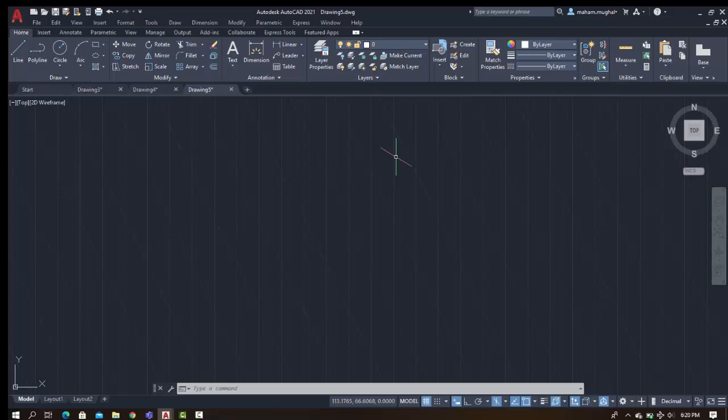That's the beginning, and now we'll start with our drawing. First of all, let's select the line command and specify an arbitrary point anywhere on your screens. I'm specifying the first point, but I want to create lines at 150 degrees and 30 degrees.